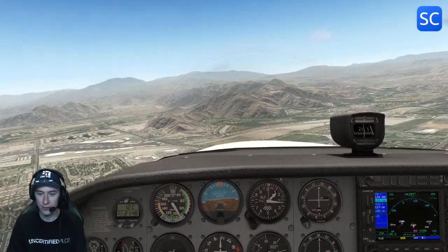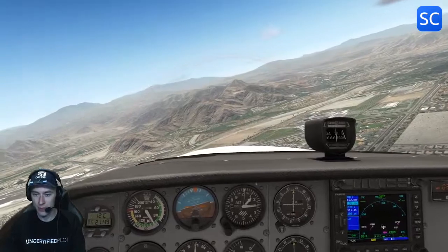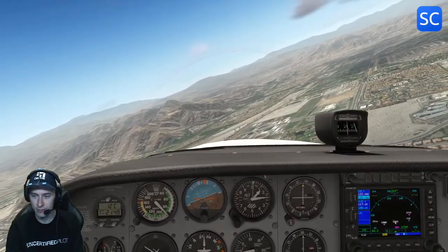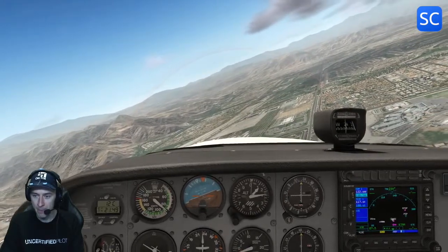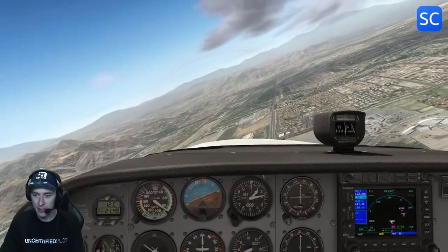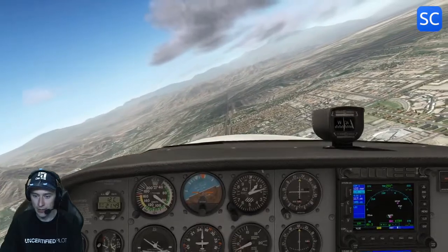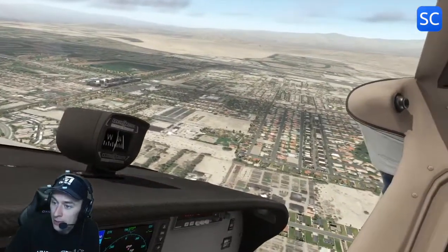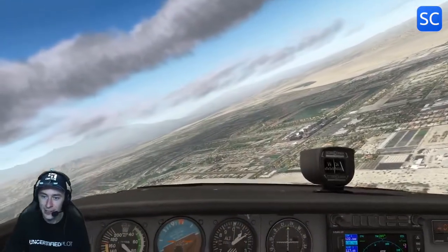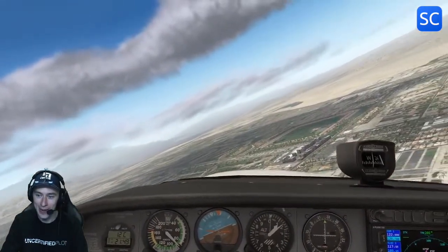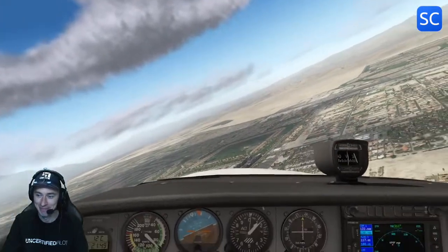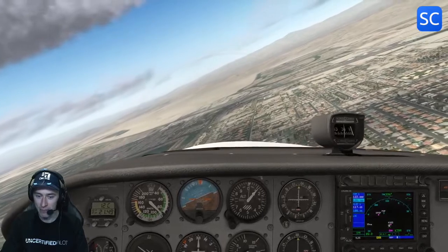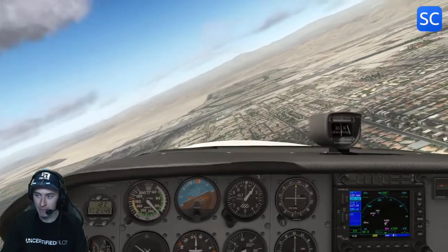Alright, let's make that turn. So already one notch of flaps in, by the way. So pulling on my yoke, so let's do a little bit more nose up trim. Keep that speed around 90, or 80 plus at least. And there we go. Look at that scenery, guys. Wow, wow, wow. Right, 1,000 feet AGL coming up, traffic pattern altitude, speed is okay.